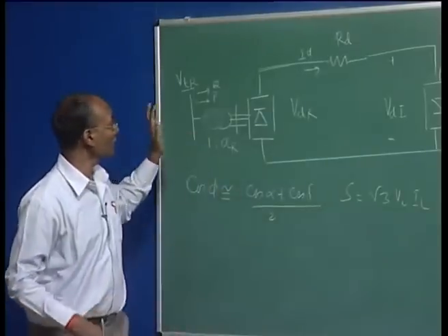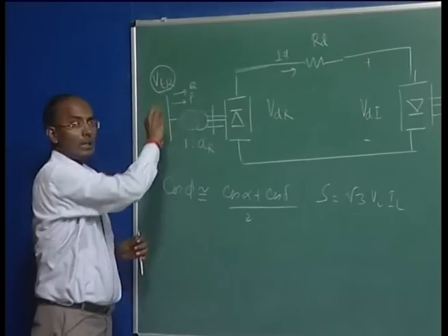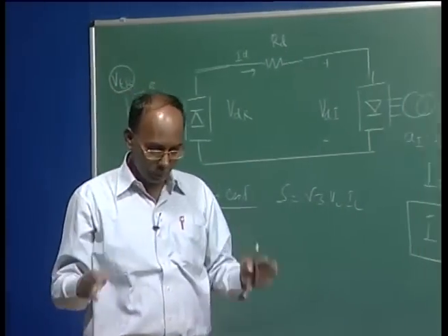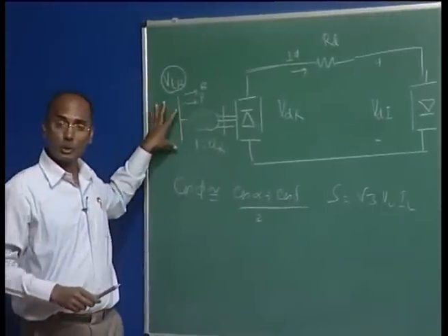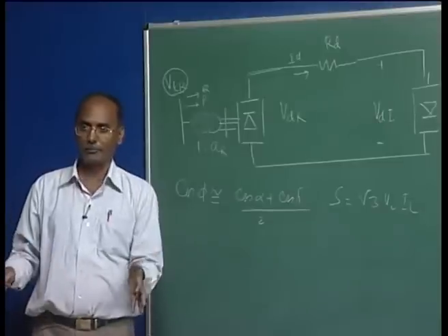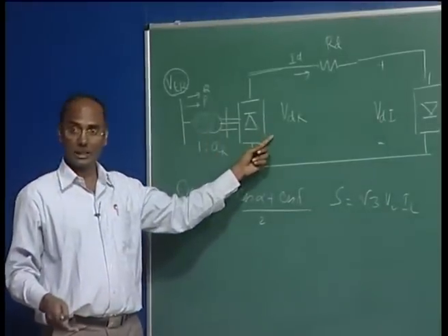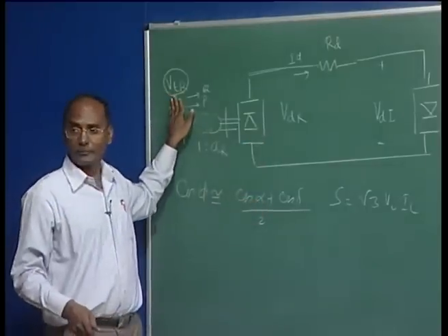So, solving this, what is happening? Now you get a different VTR. Once you solve this whole AC load flow with the DC as a load, the voltage will change, because your initial guess is not perfect. If it were perfect, you would maybe get the same. Here also we had the initial guess and solved these nonlinear equations 1, 2, 3, so it will be somewhat different.